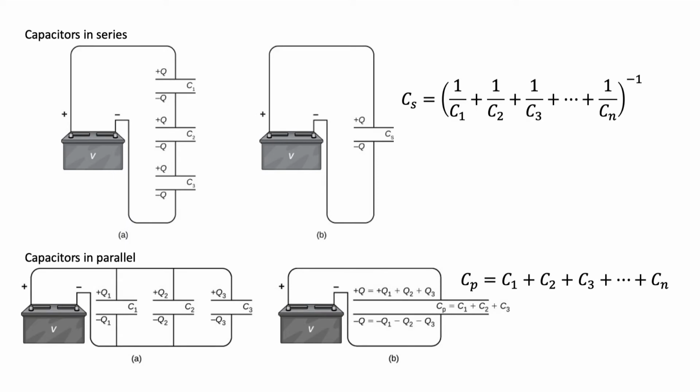Capacitors can be arranged in series or in parallel. Each capacitor in series has a specific voltage. Since voltages in series are additive, the equivalent capacitance of a series capacitor circuit is computed from the reciprocal of the sum of the reciprocal capacitances. This is easily derived through the inverse relation of the capacitance and the voltage of a capacitor, and thinking that the charges in each of the capacitors is the same for all capacitors in series. This is true because the current is the same for all capacitors in series.